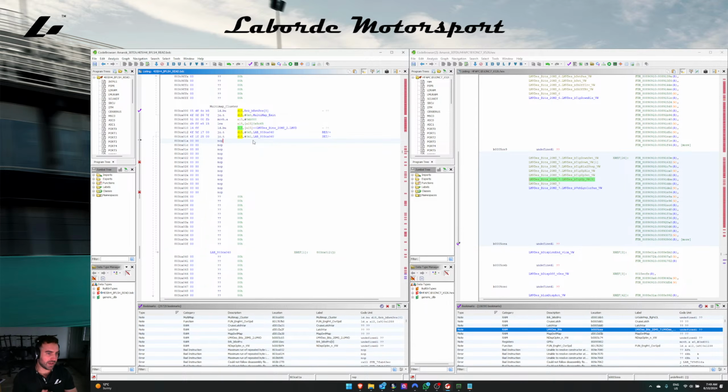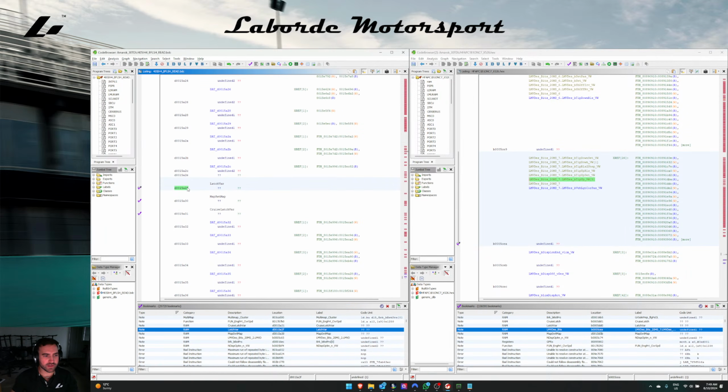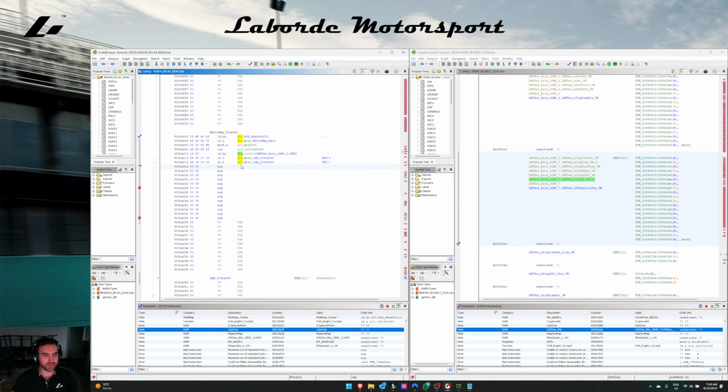Okay, so once we've checked that, I like to check the latch variable, and we'll do that now. My latch variable is stored at this address. What I'm going to try is load byte unsigned D15. If it doesn't let me load it directly like that, we're going to have to do the mov high and the load effective address.